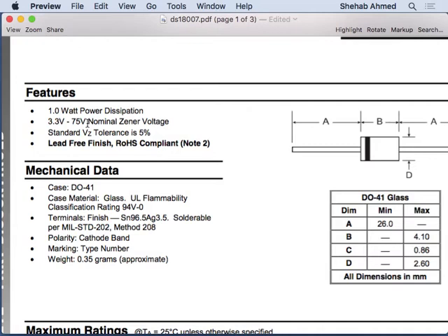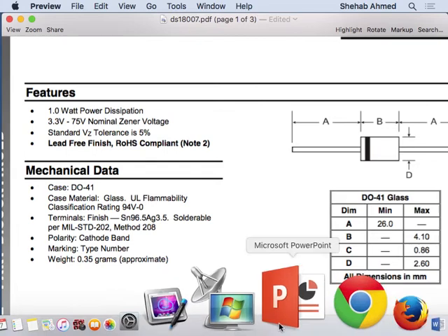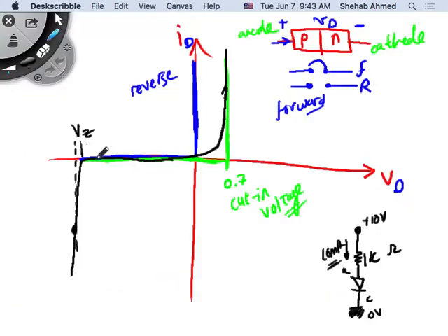So you're able to optimize your design of the diode to control the value at which this V-Zener effect happens. V-Zener effect is when you've aided the minority carrier transport across the junction considerably to be able to increase current, right? Because we said that saturation current is low. Saturation currents are low. Here I push so that it's almost zero.